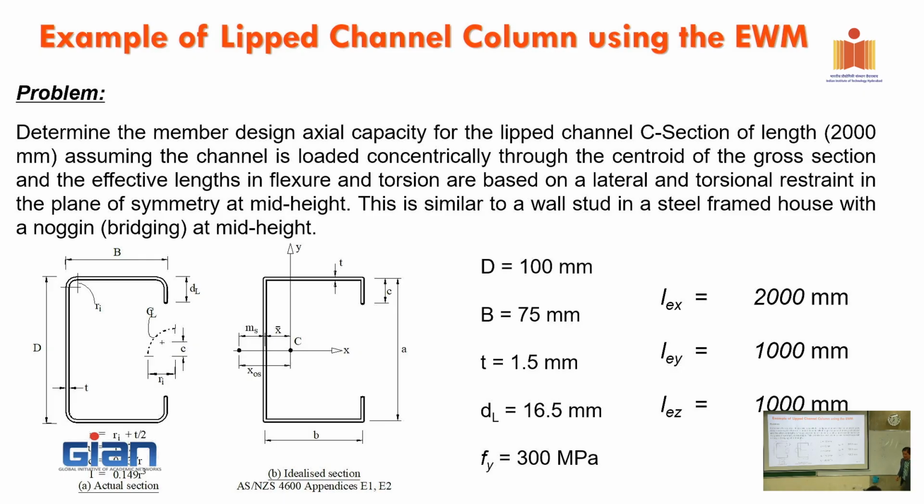Okay, so now just see that you have three different failure modes. That is pure buckling mode. This is buckling about X, buckling about Y, and torsional buckling load. And then we calculate. Right, so the reason why we have to make that section a little bit different with this one, the difference is here we make it a square one. It's not a rounded one, as you can see.